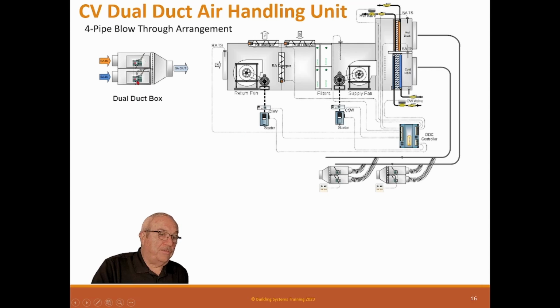So we actually have two VAV boxes, that's what they are. But they have a common sensor downstream, so they're a constant volume. Both these will modulate. So this is a modern version, and normally these are just two VAV boxes, but they have special routine software in here to make them a dual duct constant volume system. And we have a pitot port grid that's downstream instead of upstream like normal. So the downstream keeps them constant volume. So these will modulate to temperature in the space, but this Velocitrol never lets them get below or above flow, makes them constant volume.